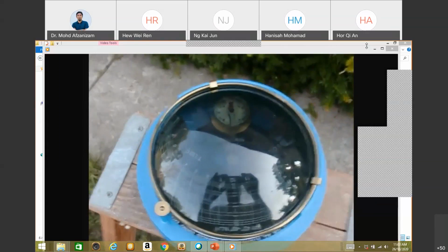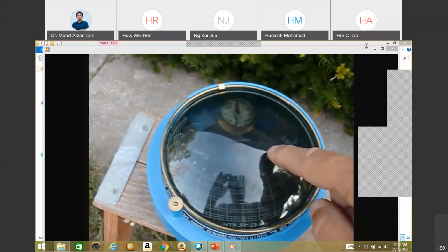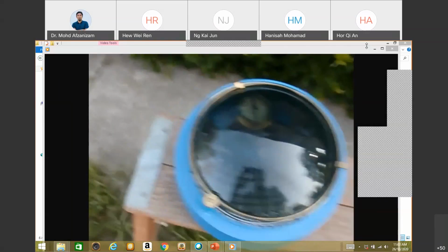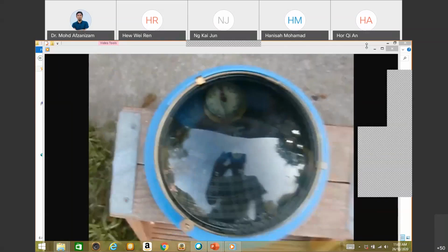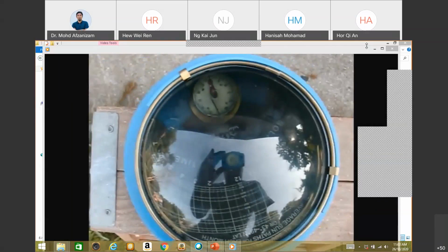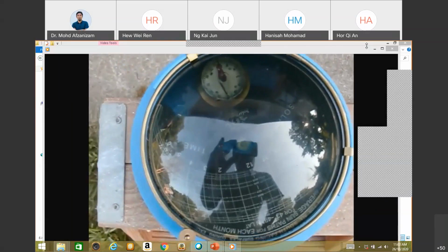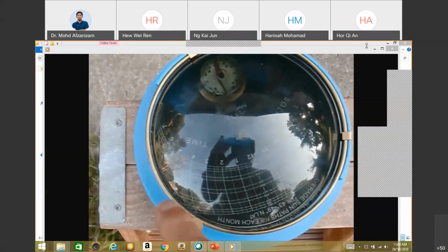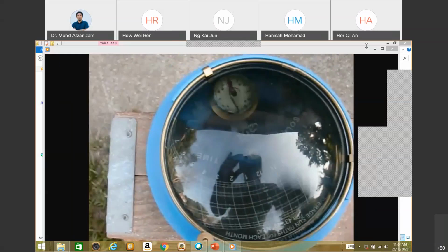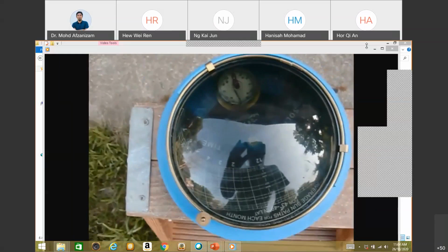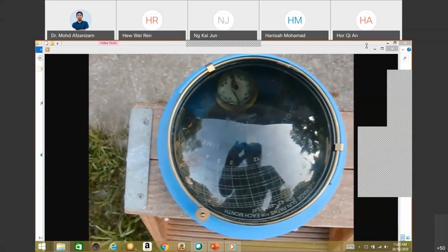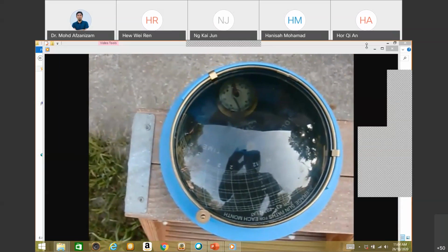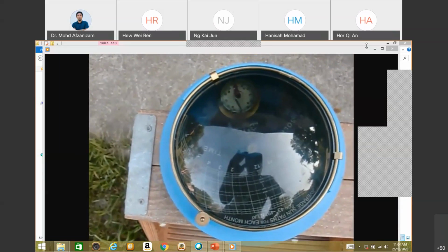Okay, so I got the dome on. You can see the outline of the trees, of the house. Some tree shading over here. Actually, the right way to do it is straight down on it, so I'll try to get centered right over that middle bubble level. You can see the shading of that tree that I mentioned earlier off to the east. I got some to my south and some to the west, and then I got up to the house to the north that will block some of the sun for some of the month. So let me take a photo of this, and then on the computer, figure out how much percent of sun I'm actually getting through at this location.